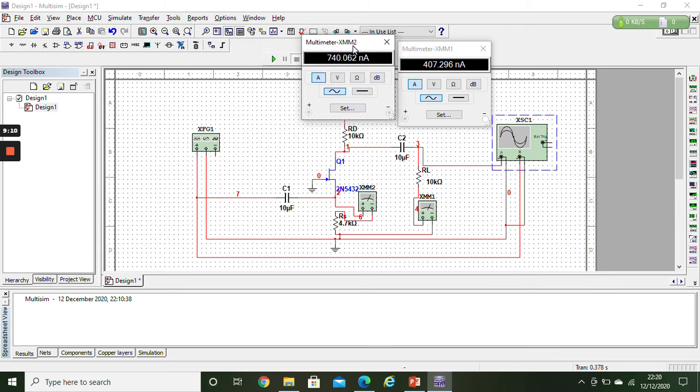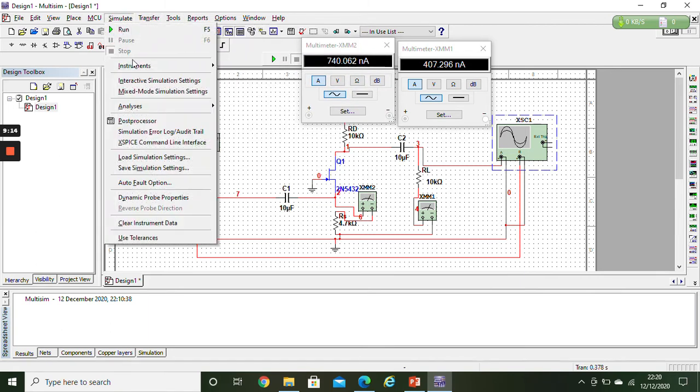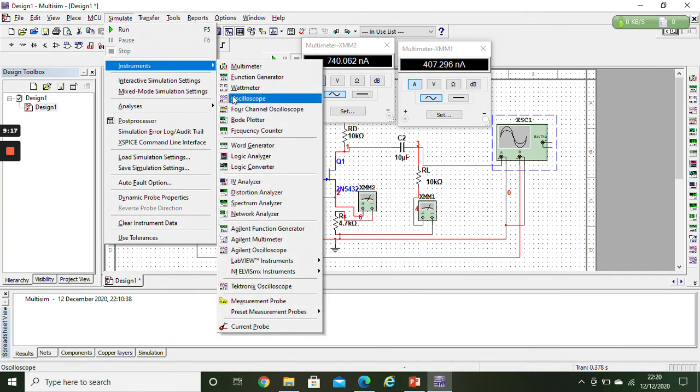So let's just add one more thing and move toward your simulation. All you would be doing in this lab is that you have to take the input voltage values and the output values with the help of your oscilloscope, and then you will be calculating your gain. The three labs, common source, common gate, common drain, were with using JFETs. Change your JFET if you want to. Just use a p-type and just flip VDD towards -15 or -10, right?